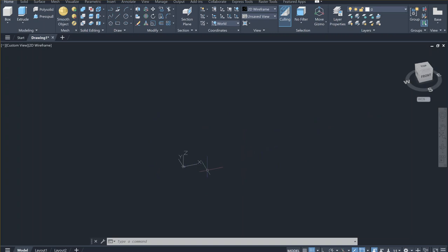Now, why am I making a big deal out of this? Well, there are certain things I know about AutoCAD that, for example, this is going to be a convenient tool for you and enables you to understand other operations later on. For example, you can create a line, any line, on the XY plane only. But if you want to create any line in the 3D world, XYZ space, not plane anymore, then